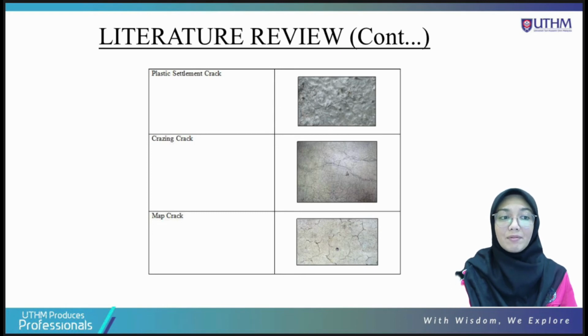It can be found in almost any concrete construction as a result of alkali silica reaction (ASR), as well as concrete drying and shrinkage. This crack form can be prevented by avoiding the addition of water or completing the work while bleeding continues.